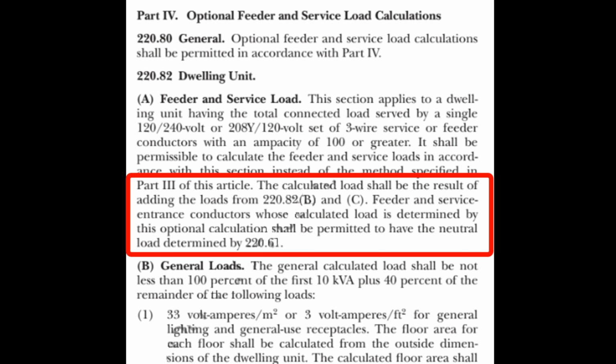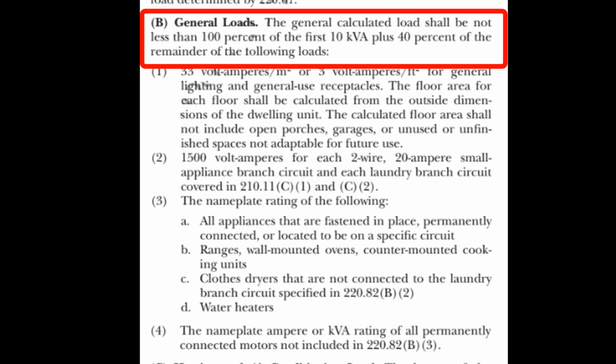I'm not concerned with calculating the neutral load because that's really only needed if you're running an undersized neutral. We shouldn't normally be doing that. Neutrals shouldn't be undersized like they used to, given the increased harmonic distortions on them by modern electronic equipment. The SE cable used to feed the subpanels in this house has a neutral that's the same size as the phase conductors.